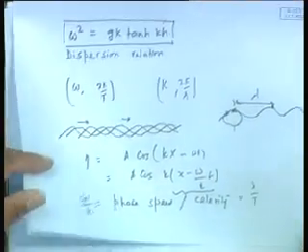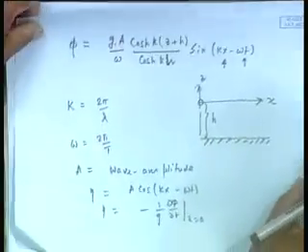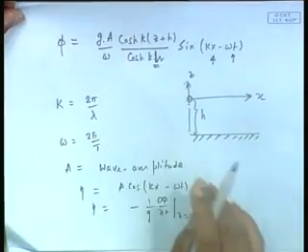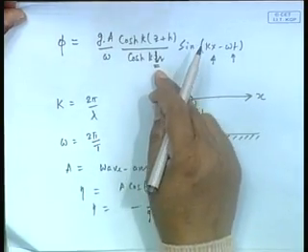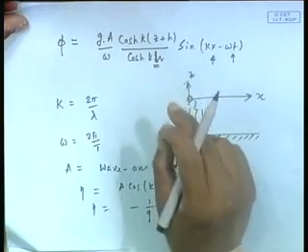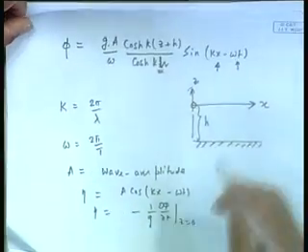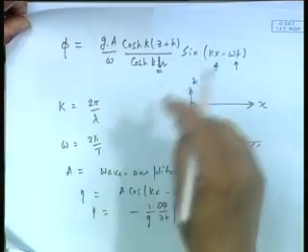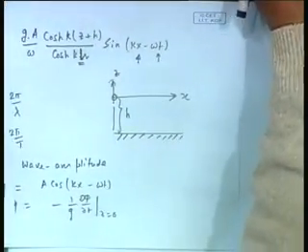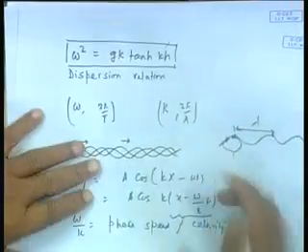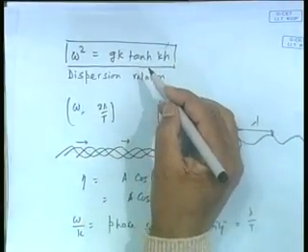Now having said that this omega square etc., now I will actually come to one simplification. What is happening here, you see that in this expression, this is all for water depth h. Now for example, if h was very deep, in other words kh is like 2 pi by lambda into h is very high, tan h kh will tend to actually 1, like this relation, this gk, this tan h kh, this will tend to actually 1, and even this relation will all simplify.